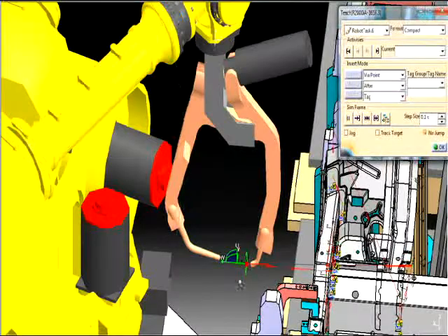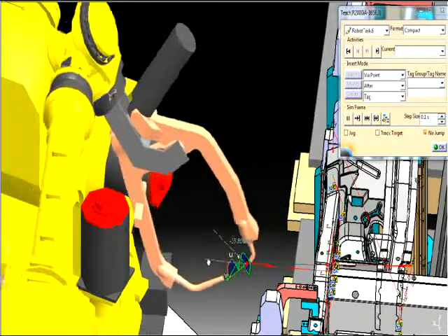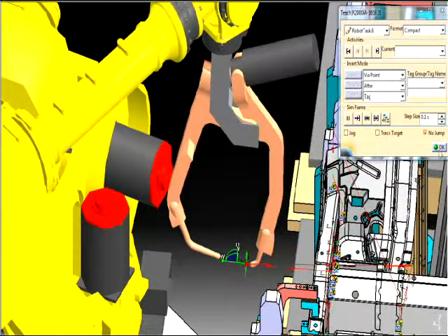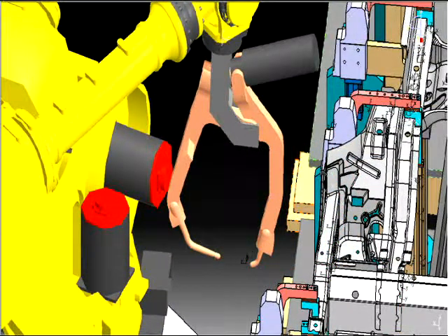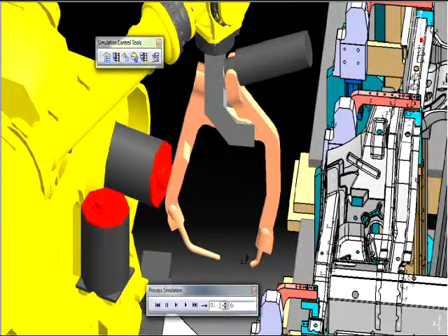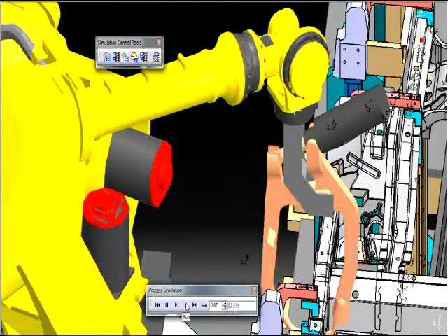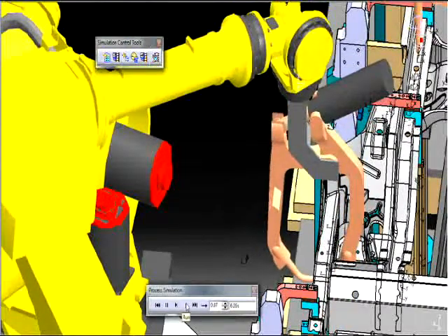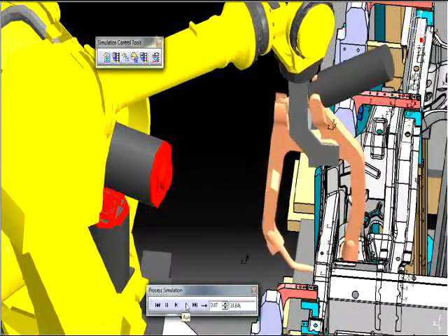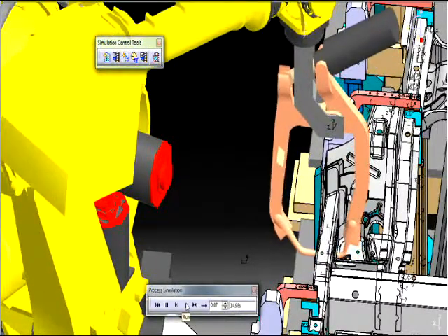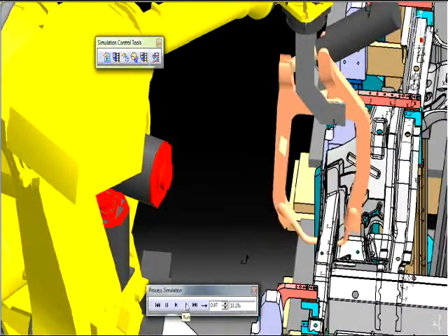And you know, there are certain other parameters that the robot needs to consider when it calculates motion, like its tool point location. When a weld gun's mounted to the robot, the operator wants the robot to calculate motion according to where the weld tips are located on the gun. Once the engineer provides this information, the software automatically inputs it into the robot's controller in the simulation. This allows the robot motion to consider the tool point location when calculating different motion types, like linear or circular. This function also can be used in fixed tool point locations, like with pedestal welding.